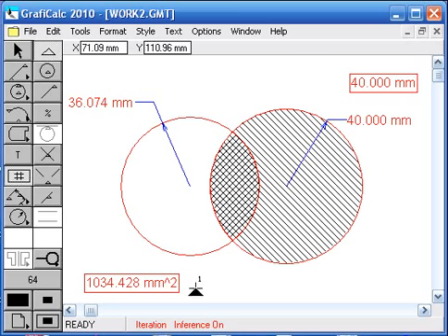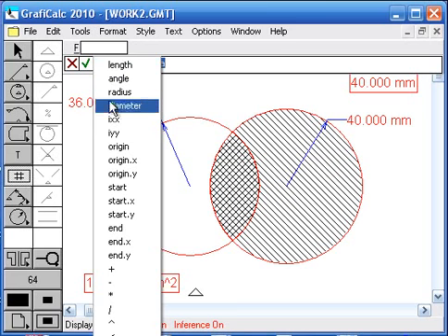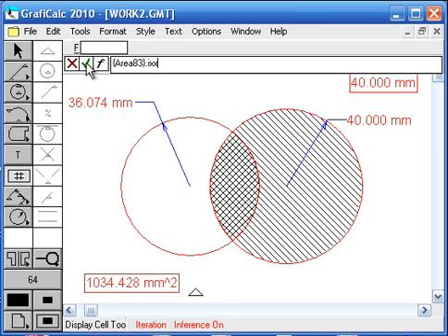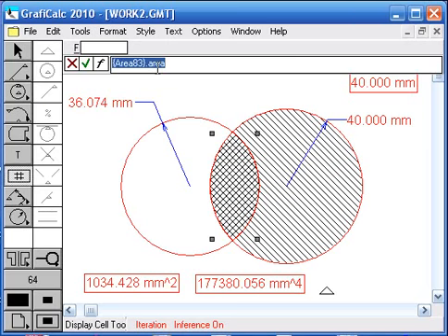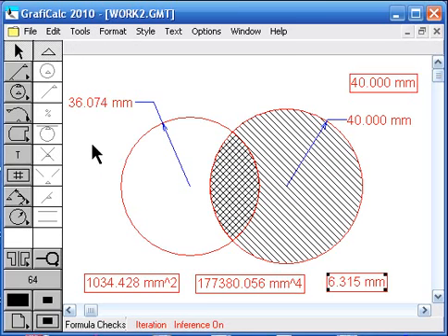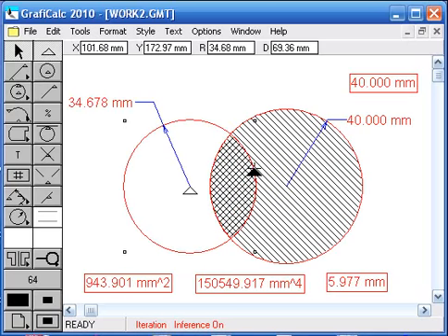I will click the cell and place the cell somewhere in the sheet, and I can select the built-in function and select the next level of built-in functions. Our most commonly used built-in functions are available in the pull down. And if I wanted a different value, for example, I want ky, I can manually enter that and it'll give me the ky value. And once these calculations are set up, if the geometry changes, the calculations update automatically because they are geometry synchronous.